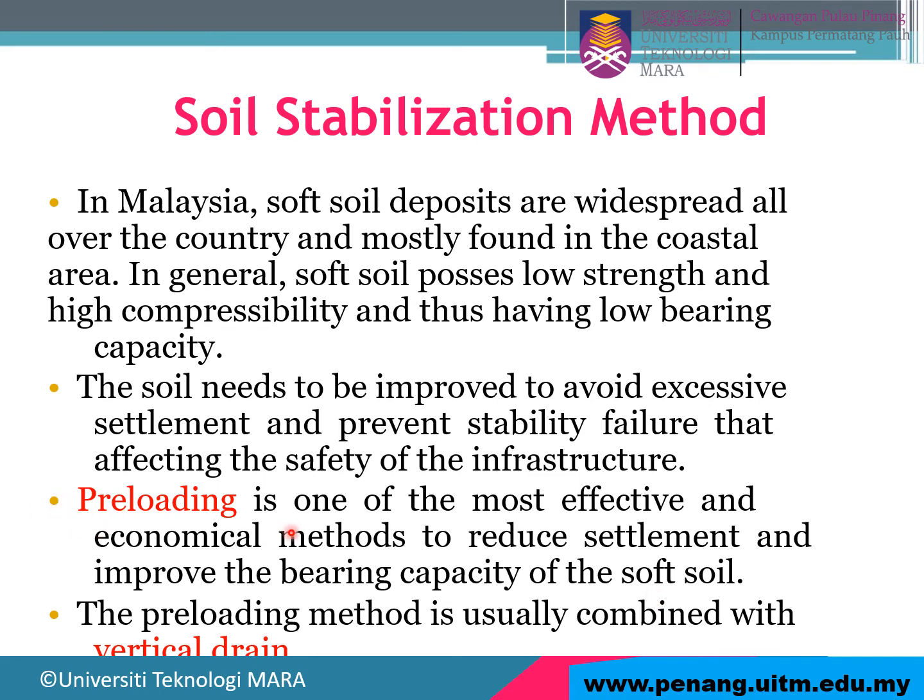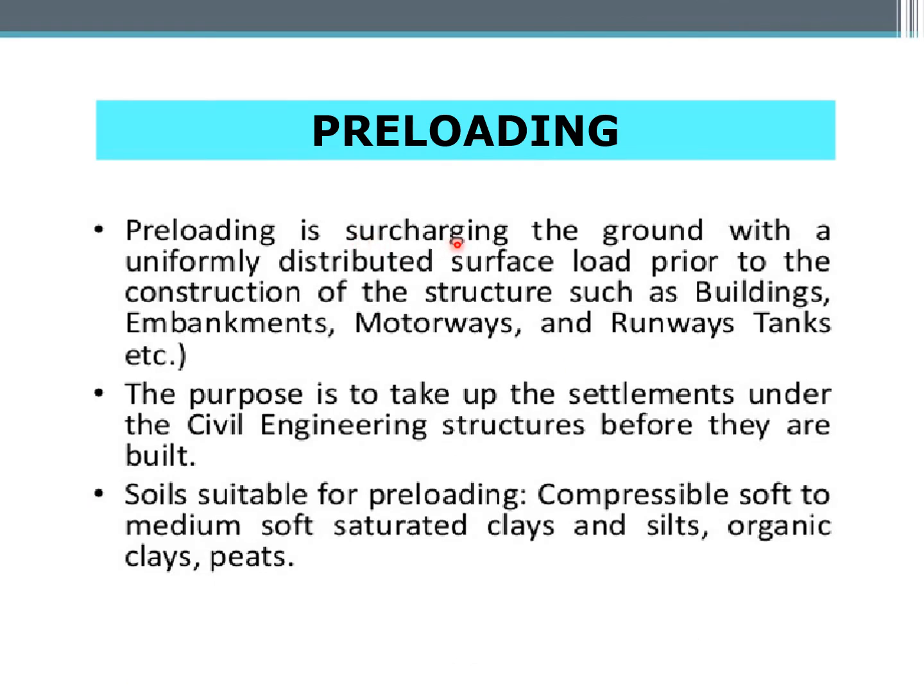Preloading is where we apply the load, and then we have to squeeze out the water by using the vertical drain. So this is a combination of preloading and vertical drain. Preloading is surcharging the ground with a uniformly distributed surface load prior to the construction of the structure, such as a building, embankment, motorway, runway, or highway.